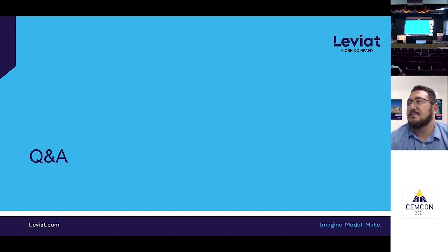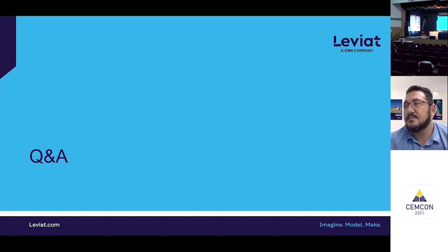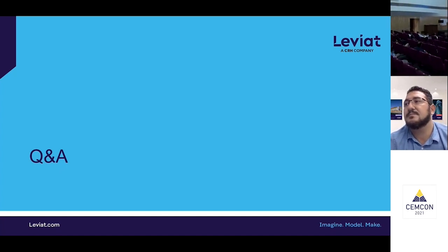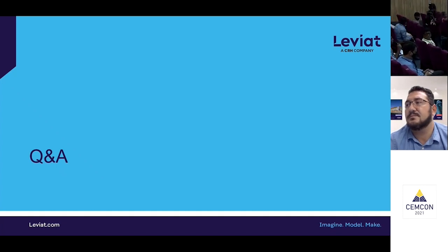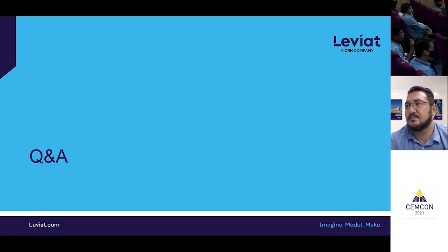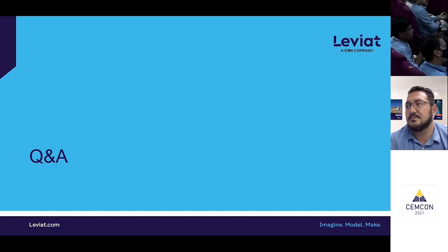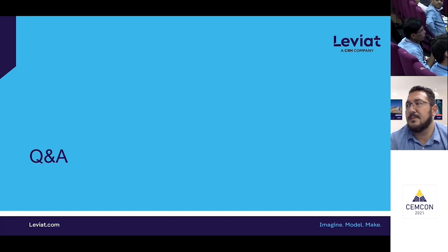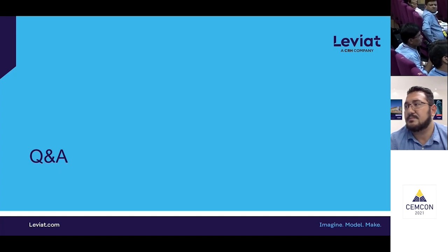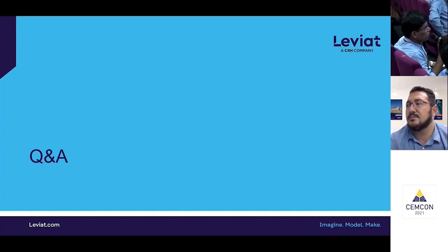Yes, hello, this is Bosle from BG Sirke. My question is, when we are lifting this wall component, which has been cast horizontally and we are tilting with a tilting station, the angle of the tilting station normally comes between 70 to 85 degrees. In that case, when we are lifting this component by the EOT crane mounted in the shed, there is an inclination while lifting.